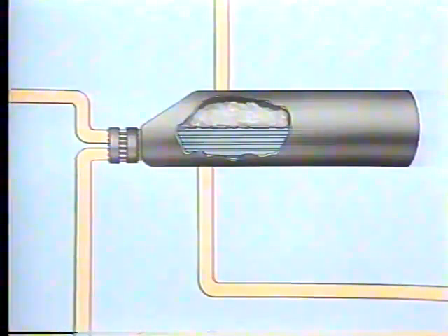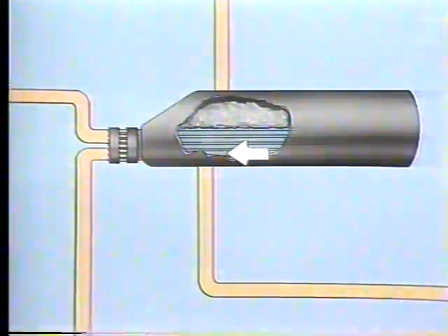The heat exchanger consists of a shell, and in the lower section of the shell are tubes. In general terms, the system works like this. Water enters the shell through this line to maintain the level in the shell at a predetermined value. At the same time, steam flows through this line and into the tubes. As steam circulates through the tubes, it heats the water, turning the water into steam that flows out of the heat exchanger through this line. As it heats the water, the steam in the tubes condenses and is drained off through this line.